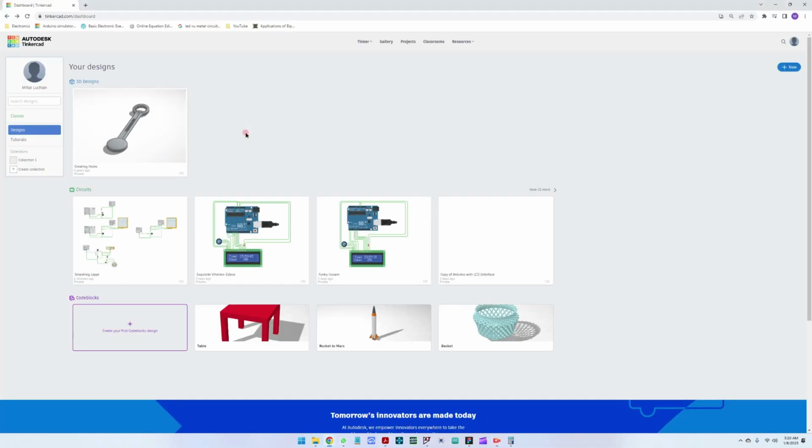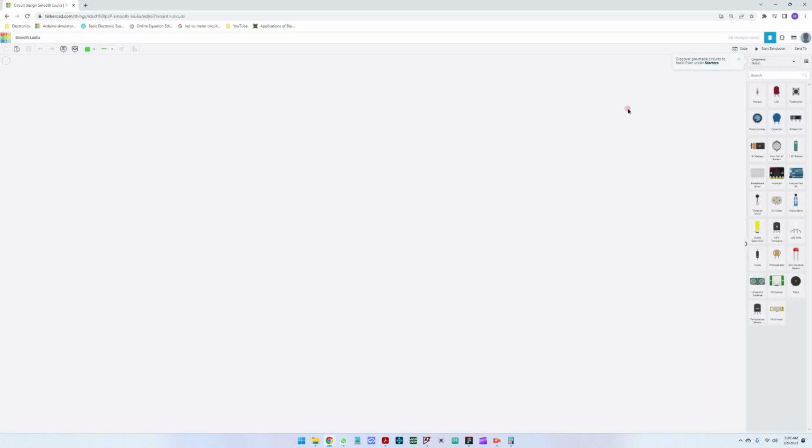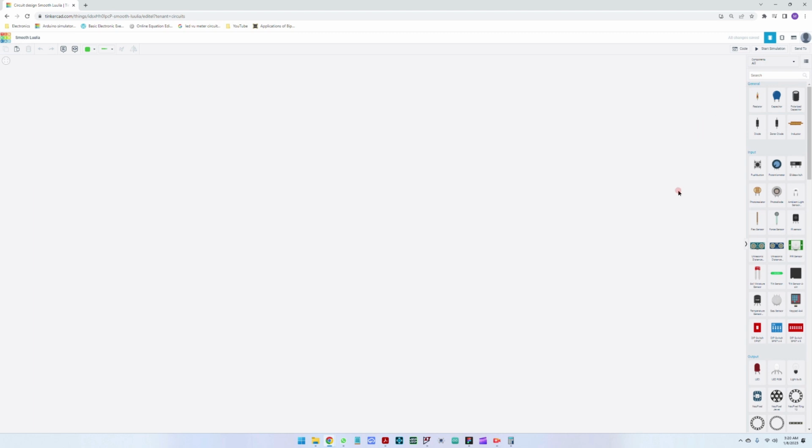Okay, so now let's create a new circuit in TinkerCad. We've used the software for most of the tutorials till now, so you could go into the resistor tutorial where I discuss a bit more about the tool. Let us first select all components, and let's search for a transistor.